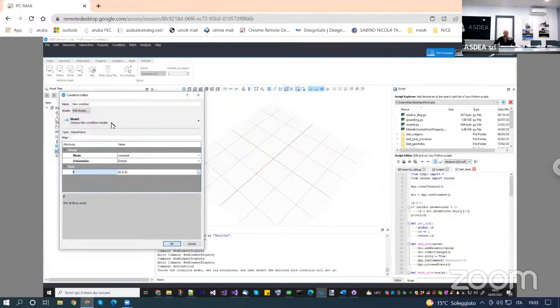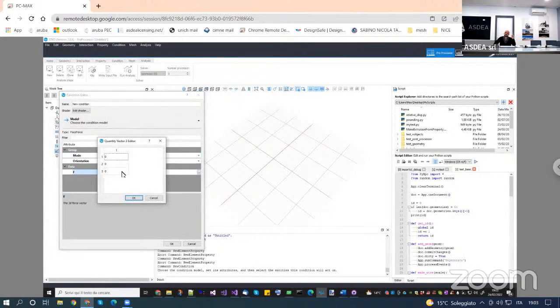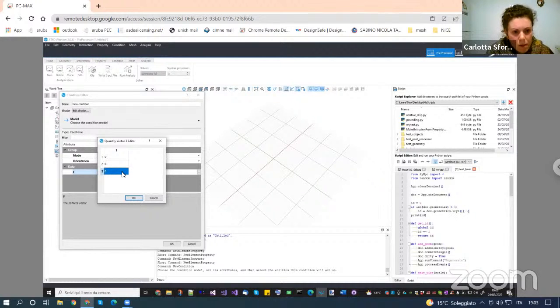If you're in 2D, so if you go on load, force, phase force, here you have to put the same value you put into the element times the thickness. Because a phase force is actually a force on a plane, so it's a force per unit area, which in your case will be the self-weight times the thickness of your model. Now, in terms of results, they will be the same. The total force will always be the self-weight times the total volume of your body. If you sum all the reactions, that will be the output.